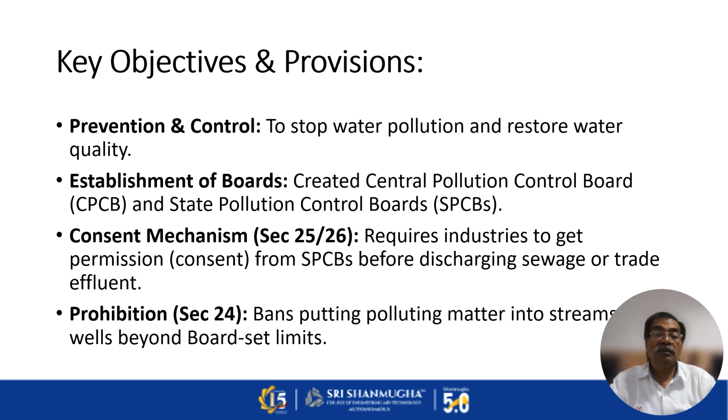The key objectives and provisions of this Water Act: first is prevention and control, to stop water pollution and restore water quality. Then establishment of boards. It creates the Central Pollution Control Board (CPCB) and State Pollution Control Boards (SPCB). Then the consent mechanism. It requires industries to get permission or consent from the SPCB before discharging sewage or trade effluent.